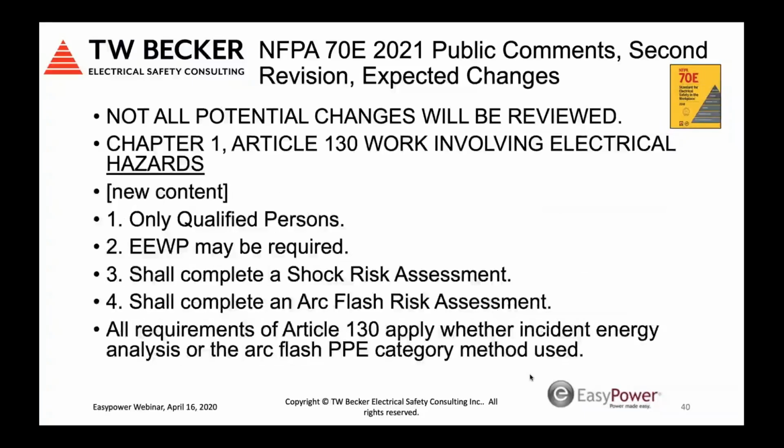So this is new content that only qualified persons should perform the energized work, that you may need an energized electrical work permit, and I want to note that there's exemptions. There's exemptions to the permit, and then again, when you do work energized, you shall complete and document a shock risk assessment, and you shall complete and document an arc flash risk assessment.